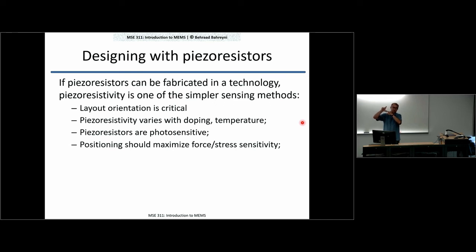Usually you don't have access to the bottom surface, so it's the top surface that you use. But where on that structure? Usually, you can find other places with larger strain values, especially if the deflections are more complex than what you get from a cantilever. But usually close to the anchors, close to the bases of these structures, is where you have the largest stresses.